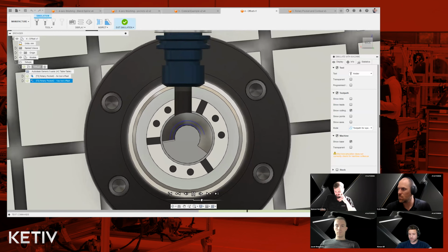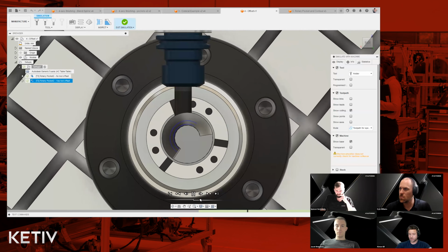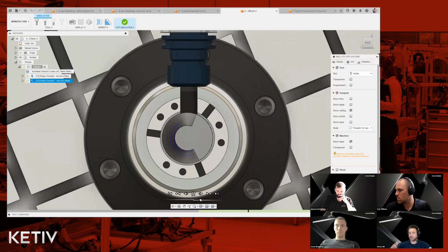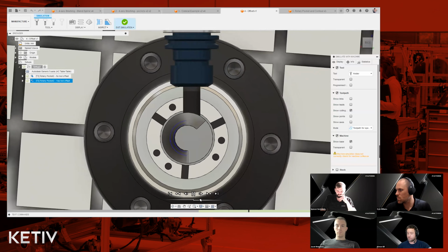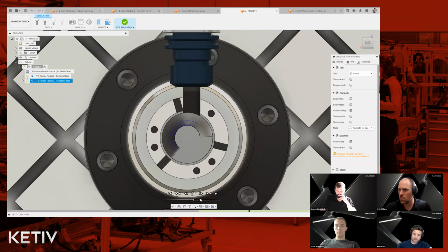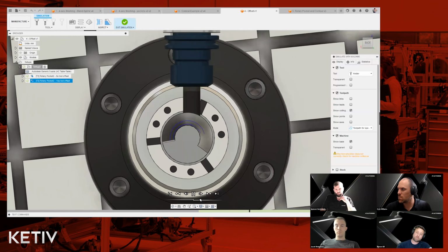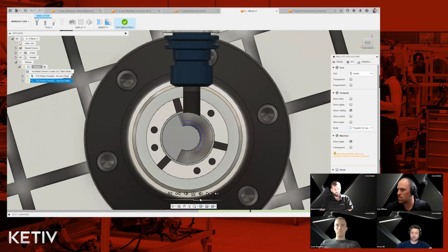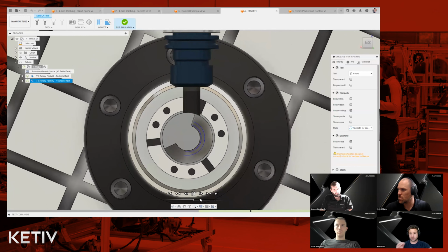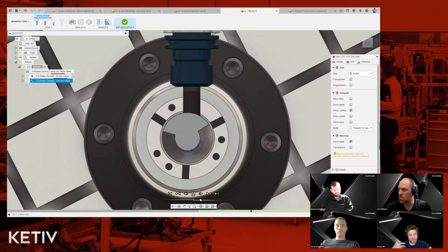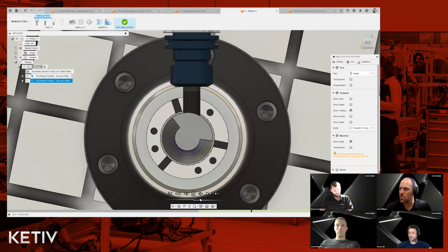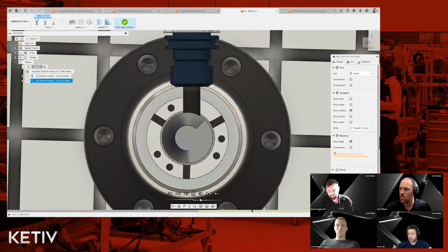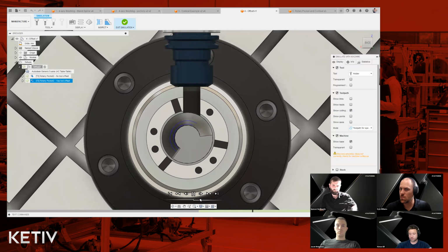Now, more importantly, as I slow down the simulation, what you'll see is it's cutting with the leading edge, but as soon as it gets to the end of that rotation, we'll invoke a linear move of the tool along in either X or Y, and then bring the tool back so that we're cutting with the leading edge on the counterclockwise portion of the tool. So this is super efficient. It makes sure that we're getting the best surface quality finish possible and that the toolpath is as efficient as possible, but we're also saving our tool life by cutting on the cutting portion of the tool.